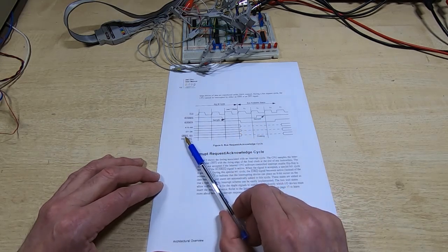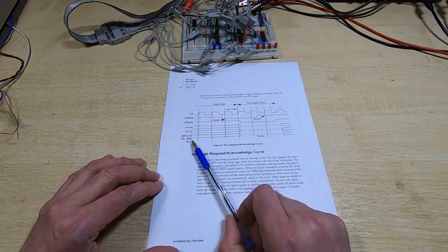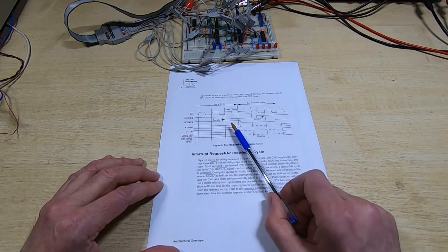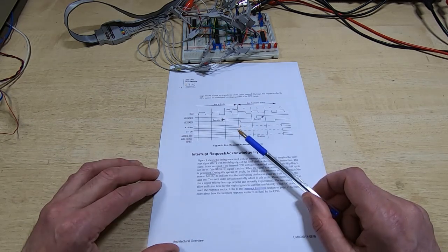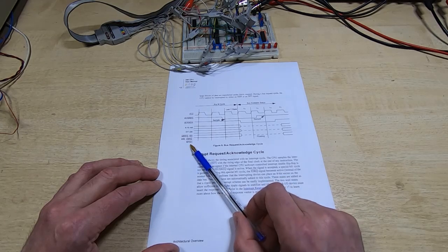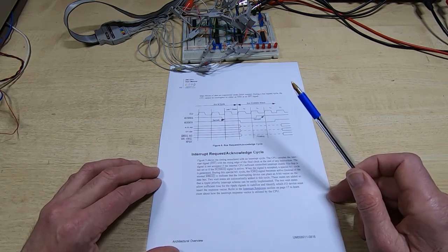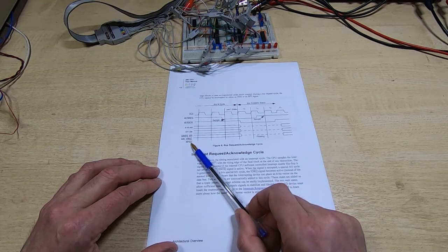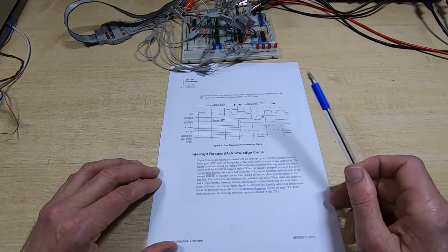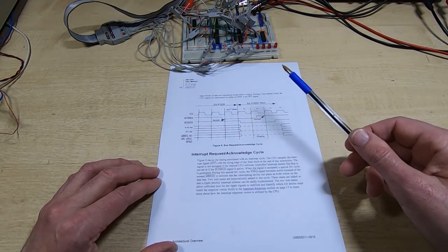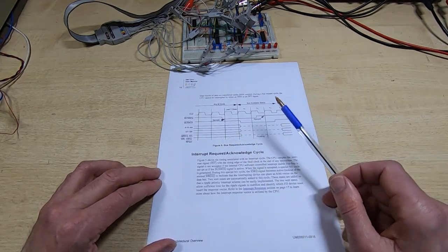The control lines it releases are memory request, read, write, in-out request and refresh. Now one important thing here is if you're intending to monopolize the address and data bus for any length of time, you will need to implement your own refresh counter and refresh cycle system, otherwise you'll start losing data from the DRAM. We're not going to worry about that because we're only using around 1 microsecond every 32 microseconds, so we're only using one complete cycle in every 32 or 33 cycles, so we don't need to worry about doing that.